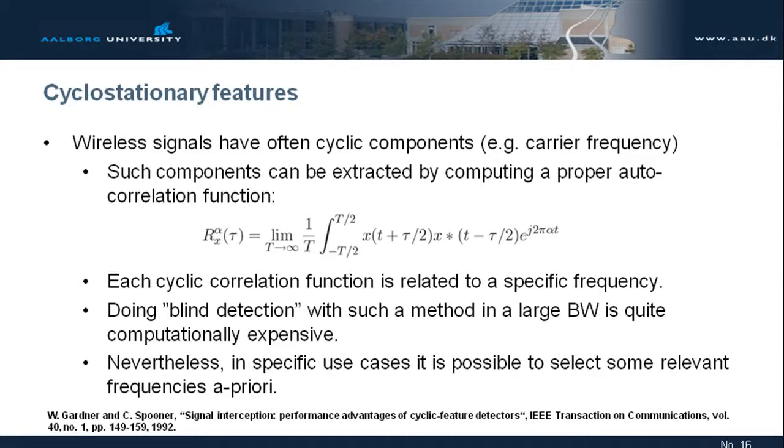Nevertheless, these types of features help you identify certain types of signals and help you, and as Louis, I hope, will show you, actively define a fingerprint to embed in your wireless signal that it's possible to detect with a cyclostationary based detector. And that's how we do frequency rendezvous, for example.